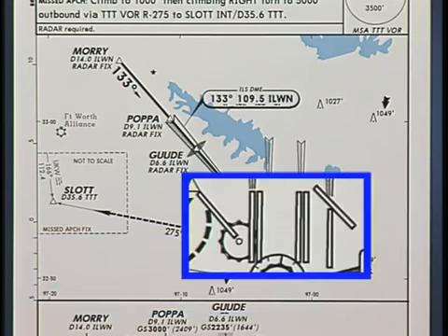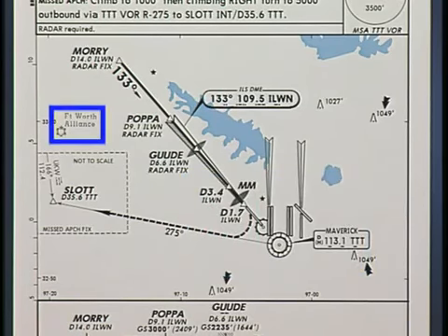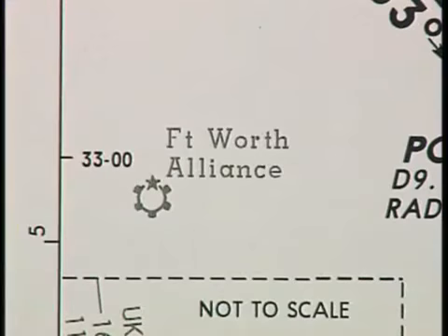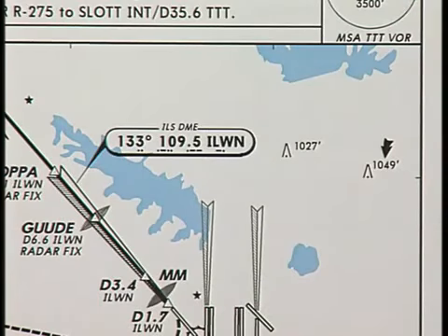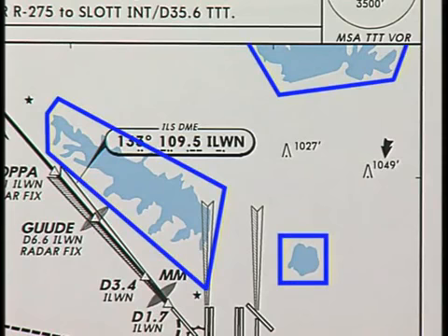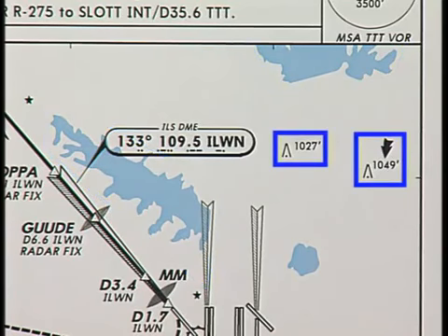The primary airport is depicted with its corresponding runway layout. For reference, airports in the vicinity that have an instrument approach or VFR airports that underlie the final approach are shown with light shading. A star symbol indicates the airport has a lighted beacon. Several types of orientation details are also shown on the plan view of approach charts. These include ground features like major lakes or rivers, as well as terrain high points and man-made structures.